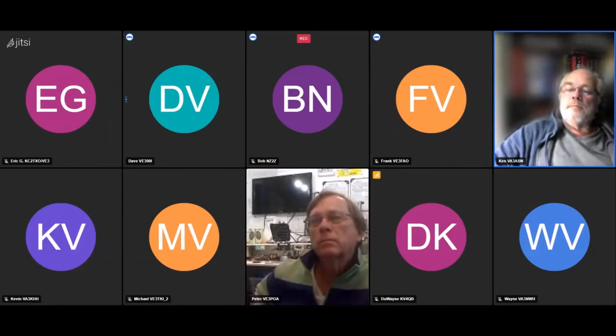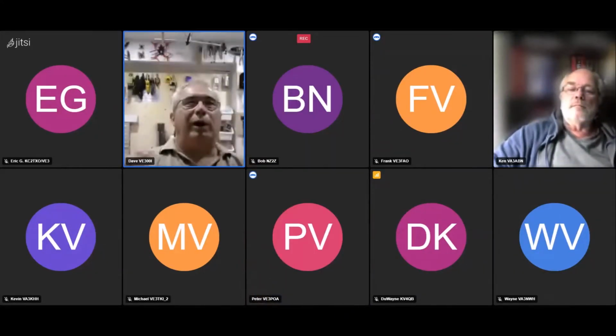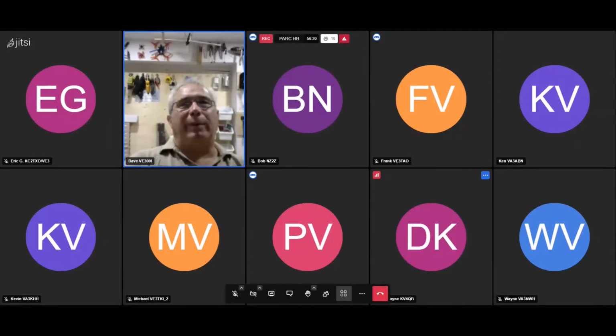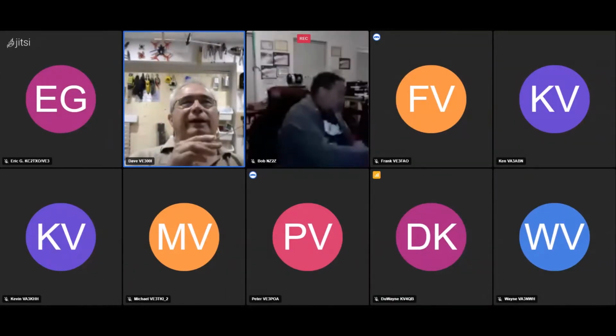The other thing, Peter, I noticed on your board, you had along the bottom a long trace that was running power to do the half voltage thing for the op amp, right? And the general rule is anytime you've got a long power trace, at the end of the power trace you've got to put a decoupling cap.